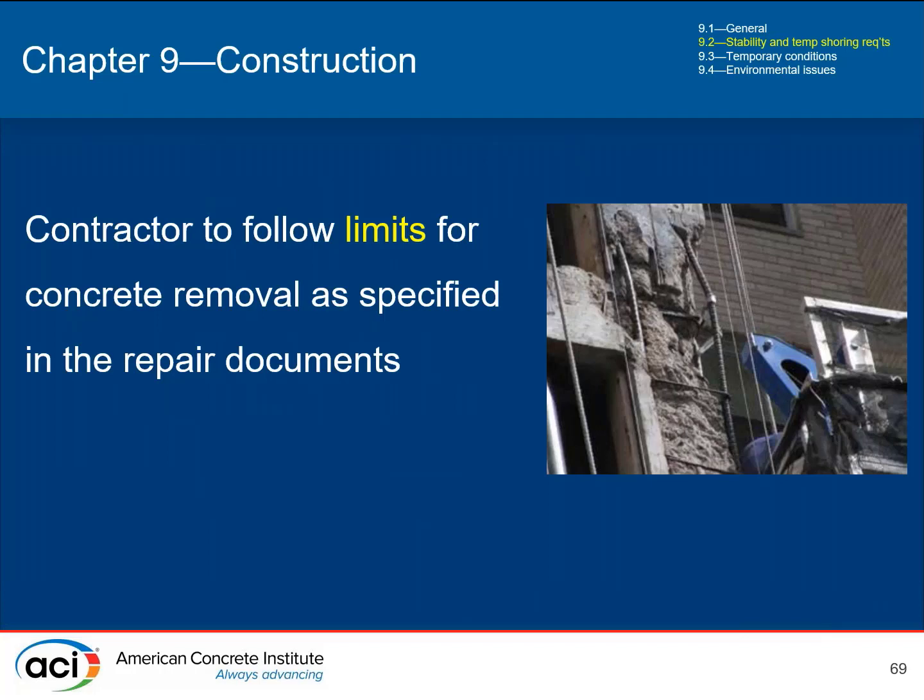But there are some aspects that the licensed design professional needs to provide, some limitations, so that the contractor knows what they can and cannot do from a safety viewpoint or a structural viewpoint or what have you. One of the critical ones that becomes very important in repair is providing limits to concrete removal. The licensed design professional, because they're the person who is responsible and familiar with the performance of the structure from a structural viewpoint, and if they have done the assessment, they're the ones that need to provide these limits.